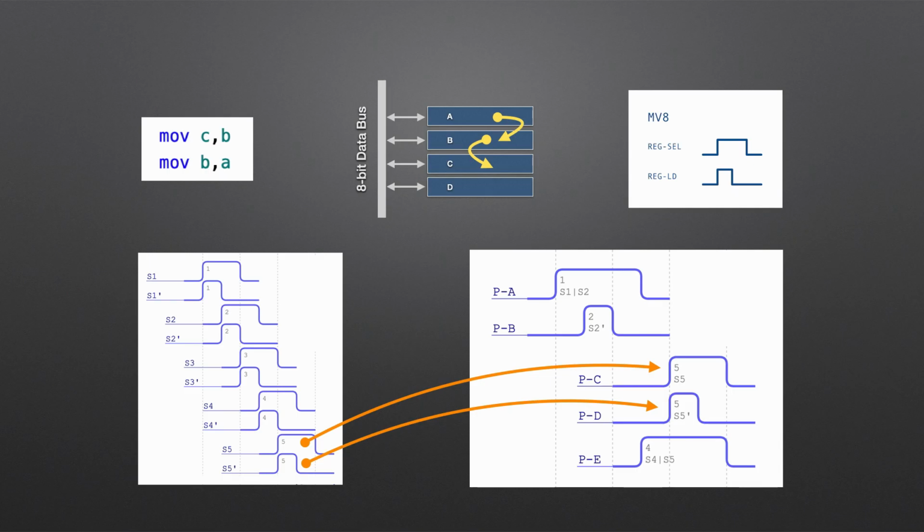Depending on the complexity and execution length of the instruction, the state machine will reset its count to 0 after 8, 10, 12 or 14 counts, or if it's a really complex instruction, it'll count all the way to 24. In the case of a move, it's a nice simple 8 count instruction.